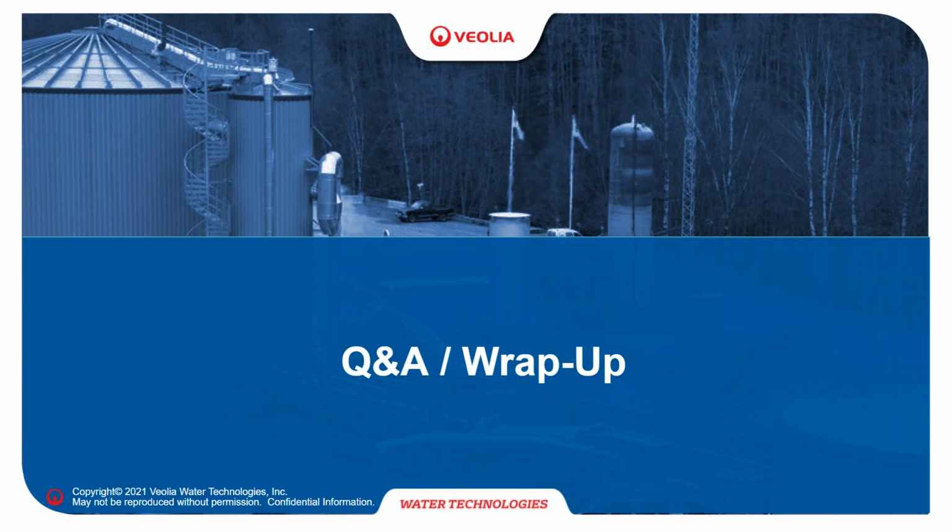Okay. Another question we have here is when you talk about the volumetric loading rate, you said you're basing that calculation on the digester volume. Why wouldn't you make that calculation based on the sludge volume in that reactor? Good question, and I don't have a good answer to that because it's really an F to M question then. It's not the sludge volume that matters, it's the sludge kilograms that matter, and that's really what your F to M is. I hope that answers the question.